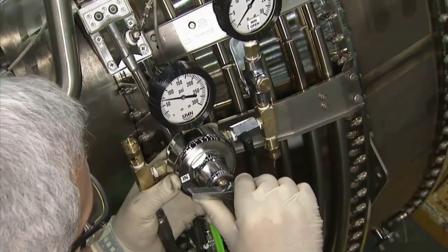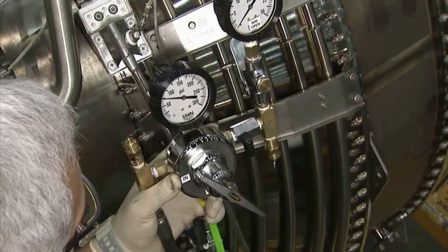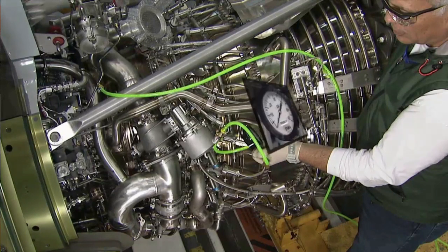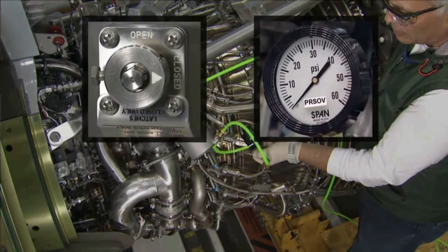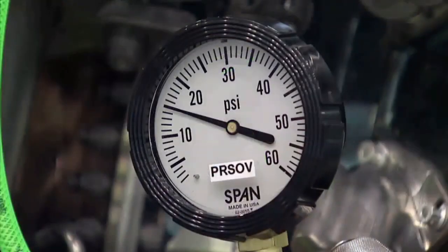It will be providing the specified supply pressure to the bar. Check the control pressure from the bar to the PRSOV by looking at the gauge on the PRSOV test assembly and observe the movement of the PRSOV as you apply pressure. If control pressure is low, there may be a leak or faulty part. To isolate the problem, begin with the PRSOV.